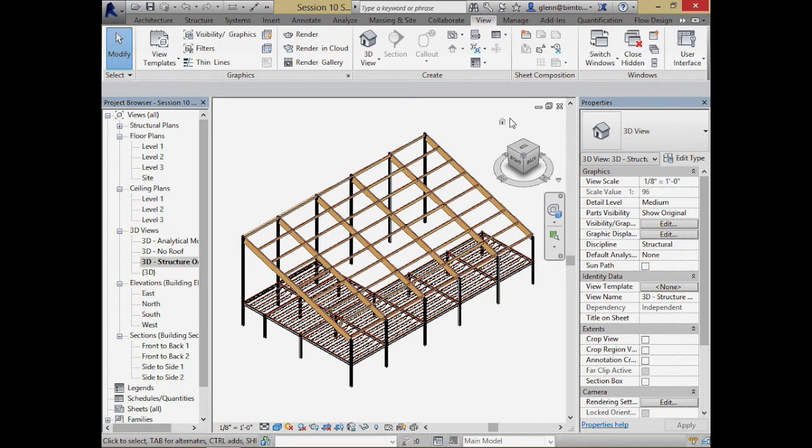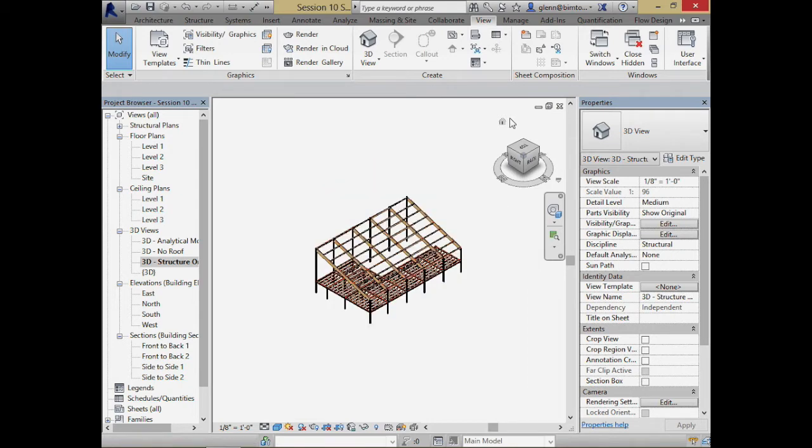But let me contrast that with about the only place where you get something very different, which is light frame wood construction. Okay? Well, concrete can be too. We'll talk about that also. There are cases where, instead of putting a lot of columns in explicitly, we just use the light frame wood walls to support the loads. And if the loads are not so concentrated that they can't be distributed nicely across the entire wall, that actually works. There are times even in wood frame construction where, I've got to illustrate this, maybe it'll be better. Let me build another little building right next to this, because I think it'll make more sense then.